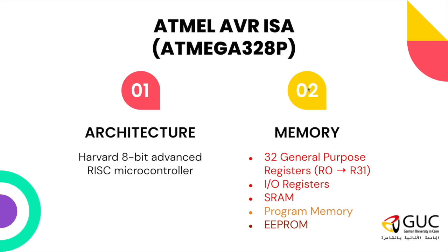However, CISC instructions are complex and perform complicated operations and take more clock cycles, because one CISC instruction can perform multiple operations, so we need multiple clock cycles to perform all of them. A CISC instruction may correspond to a sequence of RISC instructions.